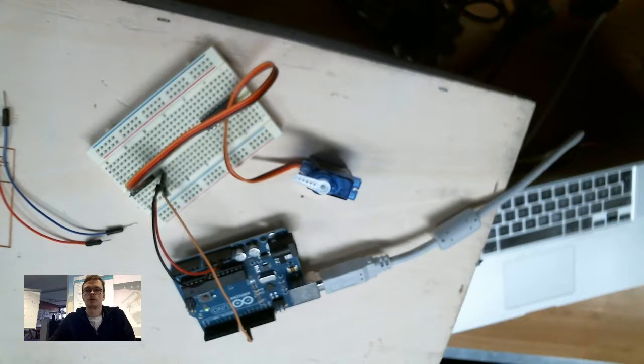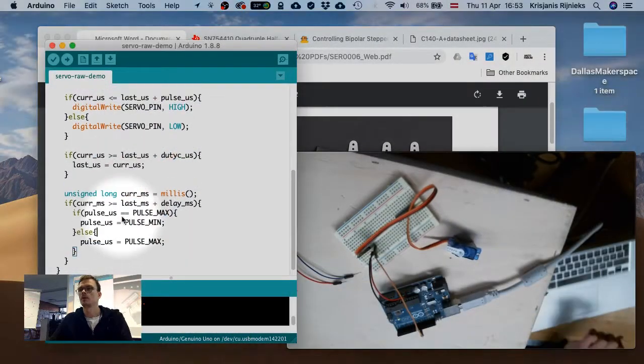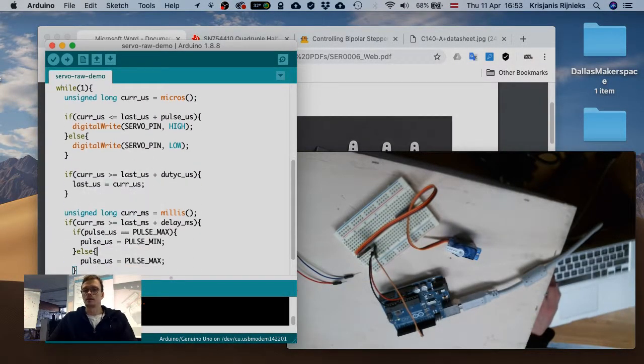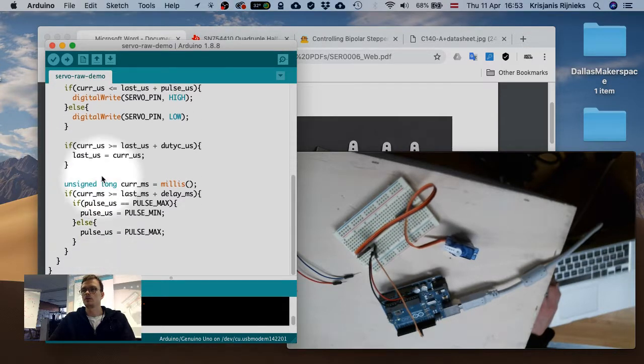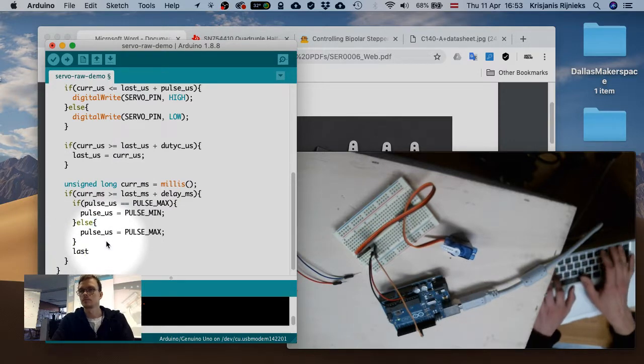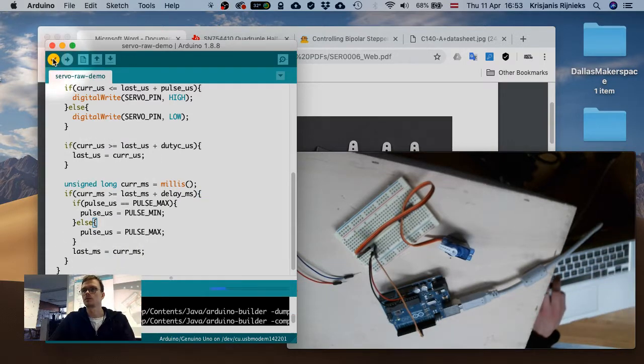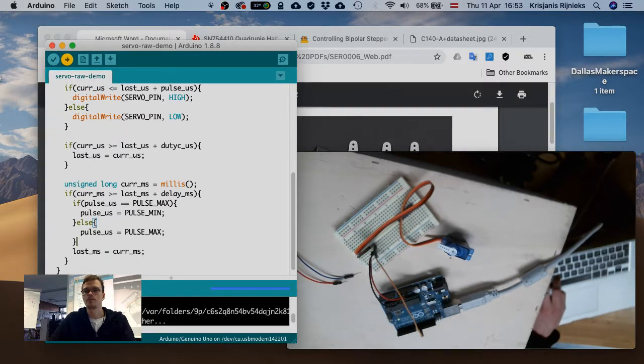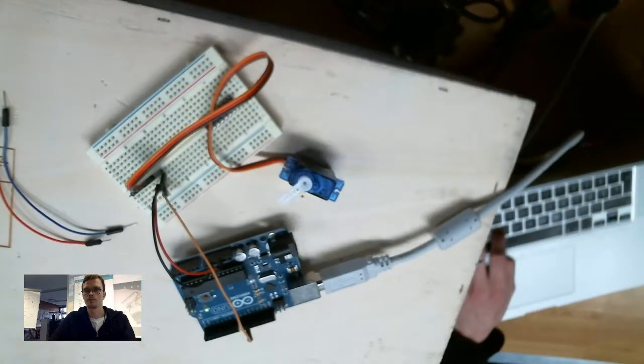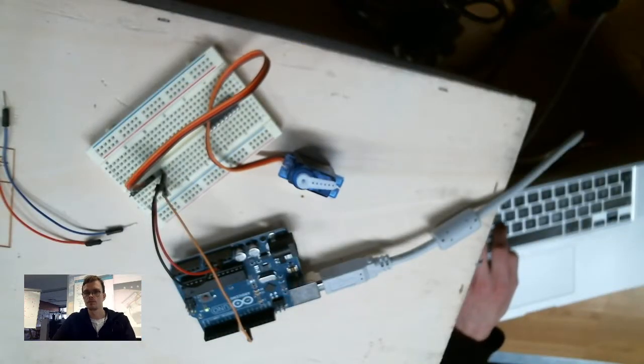Alright, something bad happened. I think I forgot one thing. After this, I need to set the last milliseconds to the current milliseconds. Like so. Let's try to verify it again and upload. Yes, now we are talking.